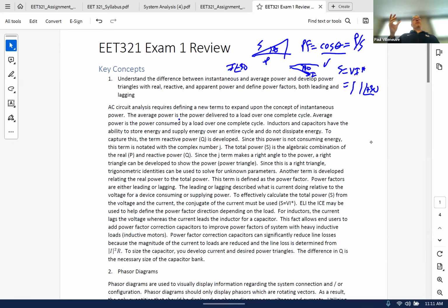So one thing we do to improve the voltage is put capacitors at the end of the line where the load is, and that counteracts the poor power factor, because in a lagging power factor, your Q is positive. With a capacitor, your Q is negative, and when you sum those together, it makes your overall Q seen from the source look like a lower number.